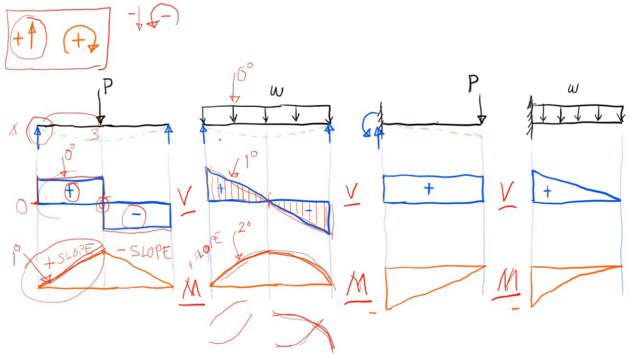Another, for this diagram here, we have zero shear here, and our maximum moment occurs exactly where we have zero shear. Now, based on this observation, we can say that the location of our maximum moment usually will occur at the point of zero shear.